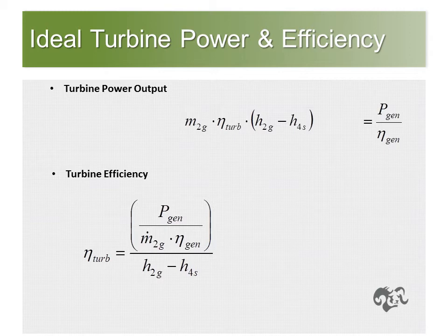Basically, you put a big filter on the calculated value so that it doesn't move around too much, and then trend and archive this number over the life of the plant. And again, remember that simple but important equation for the isentropic turbine exhaust enthalpy. Using this equation and the calculated and filtered turbine efficiency, we can calculate the specific work.